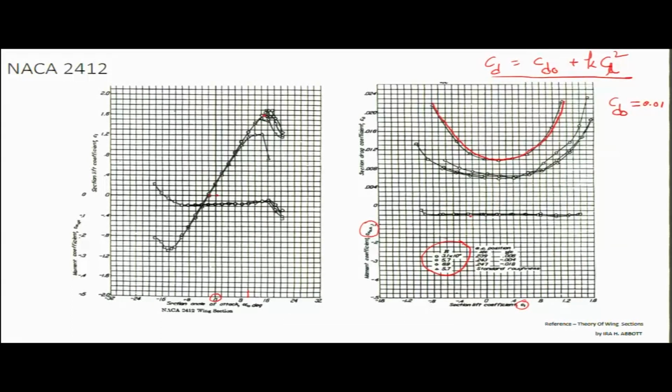So you see this is the variation of moment about the aerodynamic center with Cl, right? When does lift change? When the angle of attack changes, the lift coefficient changes. So we can infer that as the angle of attack changes and hence the Cl changes, the pitching moment almost remains constant. Although there is a variation in Cl, the value of this pitching moment remains constant at about c by 4. The corresponding aerodynamic center for this is c by 4, so this moment is about the quarter chord of that aerofoil.